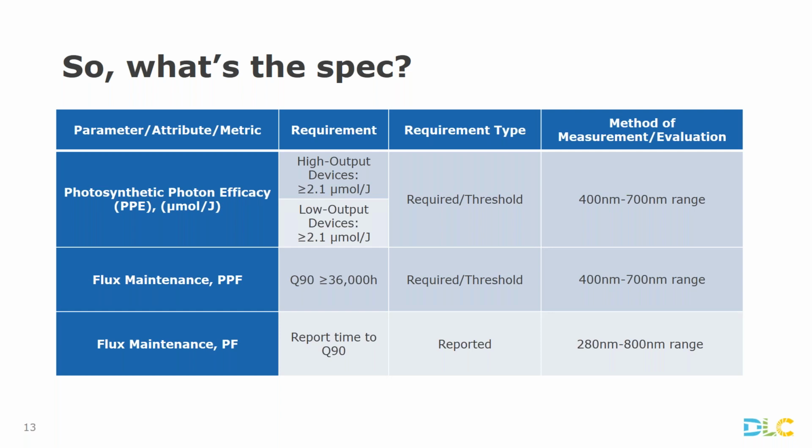So there is a question directly about why we would propose to allow products with fans. And the comment here is that fans are for sure to be the first point of failure. So I wonder if you want to give some commentary on that. Absolutely, thanks. Well, I don't want to give any assent or dissent from the assertion that fans will be the first point of failure. We certainly are keying in on them as being a potential significant source of fixture failure, for sure. If the fan breaks, the LED devices and driver will get too hot and then they will die or fail early on in their lifetime. There's no doubt about that.